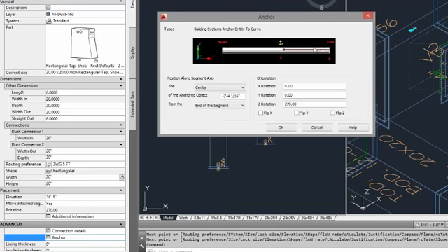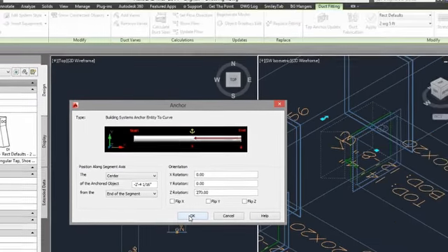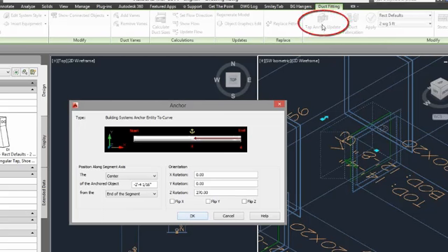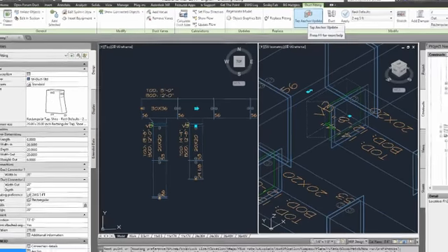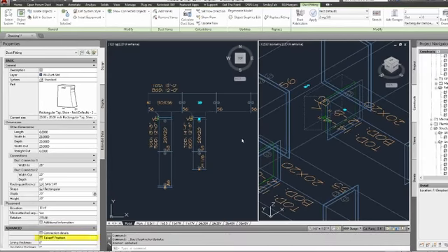That is because when you have your justification set to center, AutoCAD MEP does not put the correct anchor on the tap. To get around that, EastCoast has placed a tool up here on your ribbon called Tap Anchor Update. When you select that, that'll change the anchor to the correct anchor for a tap, and then when you come over to the property palette, again you'll see a takeoff position under Advanced, and you can select that, and that will then allow you to start manipulating the placement of that tap on that piece of duct.